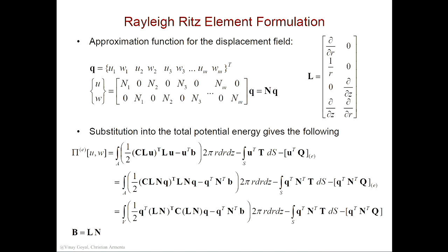And so, again, I'm going to interpolate U, so it's a function of the unknown coefficients, which are the nodal unknowns, U1, U2, U3, and so forth up to UM. Because I could have a triangular element, a square element, a second-order triangular element, a second-order quadrilateral element, Q8, Q9. Well, why would I make it generic? That way you can choose the one you want, right? So we could do that.